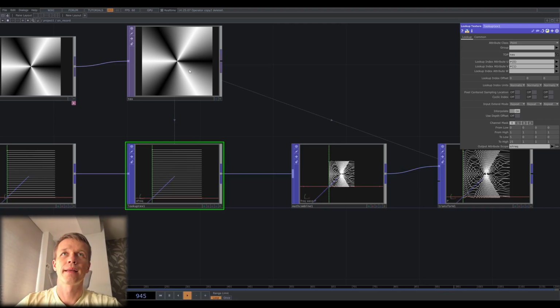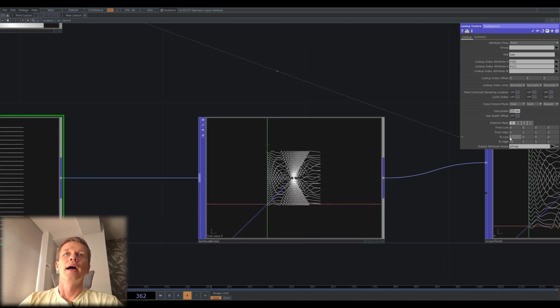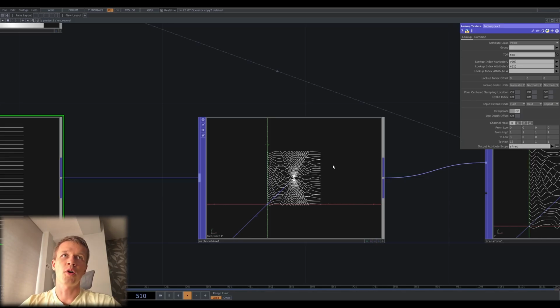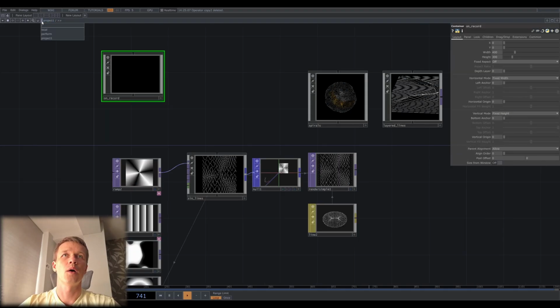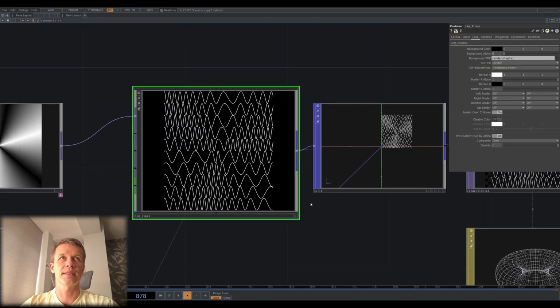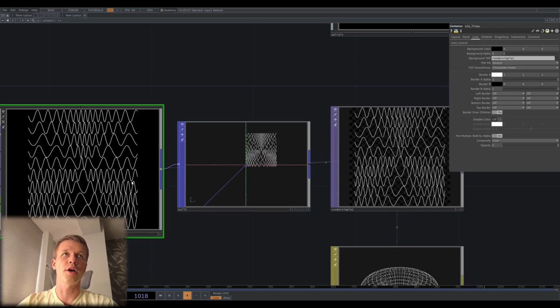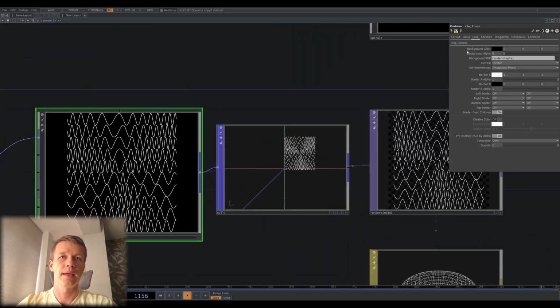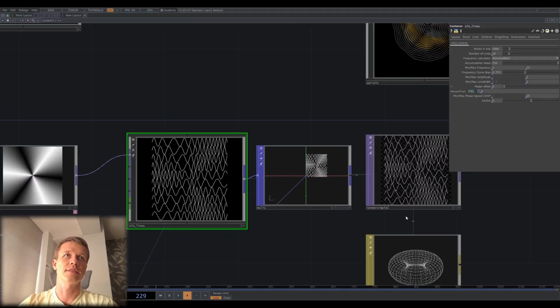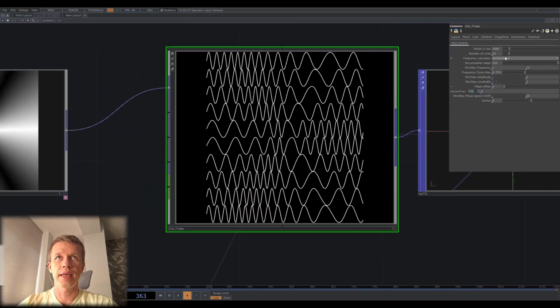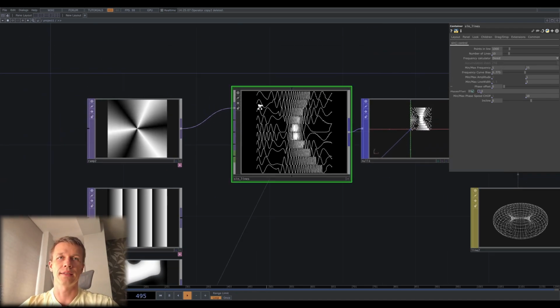Okay. Now the texture works as a frequency field, and bright areas produce high frequency, and dark areas produce lower frequency. You can also adjust interpolation and extend mode to match the texture better. And there is one important detail here. This setup uses the texture value at the current point directly to calculate frequency. In the pattern component, I also included the second method, which accumulates frequency from the beginning of the line to the current point before calculating the phase.